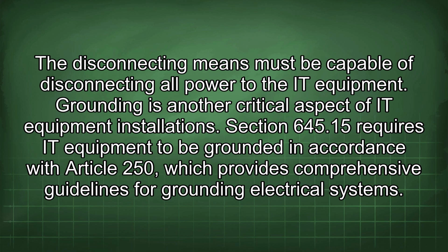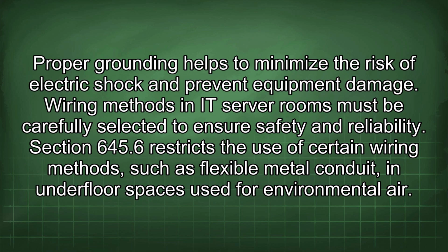Grounding is another critical aspect of IT equipment installations. Section 645.15 requires IT equipment to be grounded in accordance with Article 250, which provides comprehensive guidelines for grounding electrical systems. Proper grounding helps to minimize the risk of electric shock and prevent equipment damage.